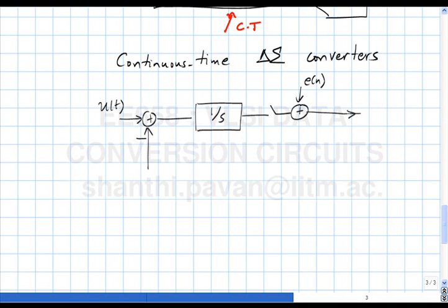So we saw that the continuous time output of the DAC has to be associated with a pulse shape, correct? And what all pulse shapes did we see? The first thing was just the simple continuous time impulse, which is like a terrible thing to do, okay? The next thing is, one other natural pulse shape is the so-called NRZ pulse shape. The other pulse shape that we know is the return to zero, and you can come up with any number of pulse shapes, so it's not a big deal. So bottom line is that there is a pulse shape associated with the DAC. Does this make sense?